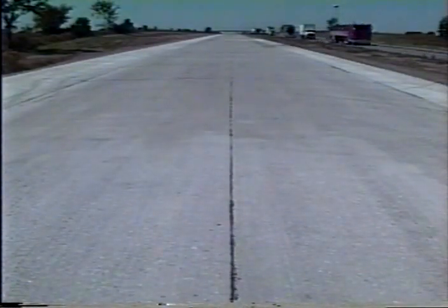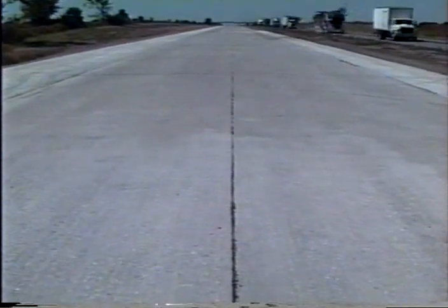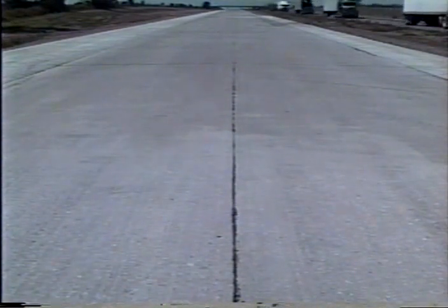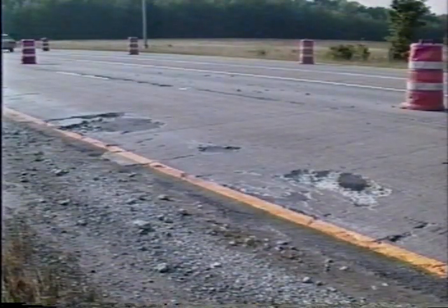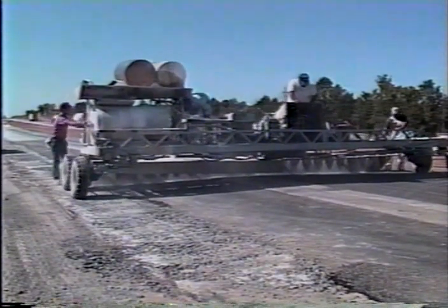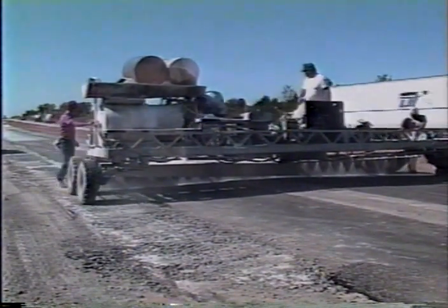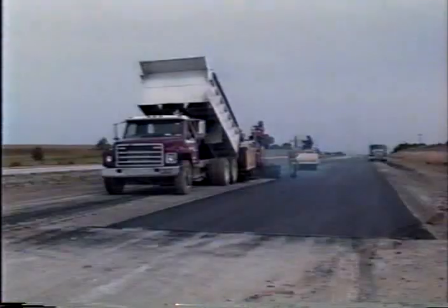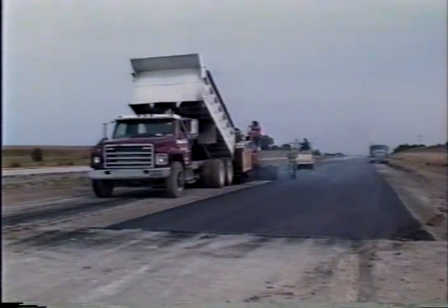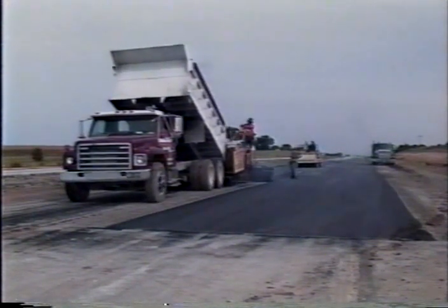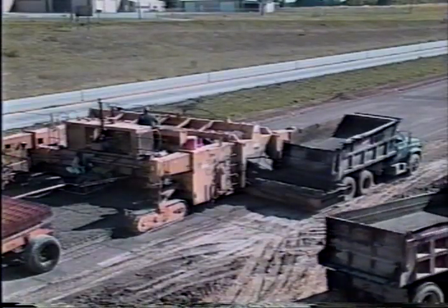Concrete overlays may be appropriate under certain circumstances. They may be either bonded or unbonded. An unbonded overlay may be constructed if the existing concrete pavement is badly deteriorated. Specific measures are taken to prevent the overlay from bonding to the existing pavement, so that distresses in the existing pavement will not reflect through to the overlay. Normally, a layer of asphalt concrete is placed as a bond breaker or separation layer. And then the overlay is placed.